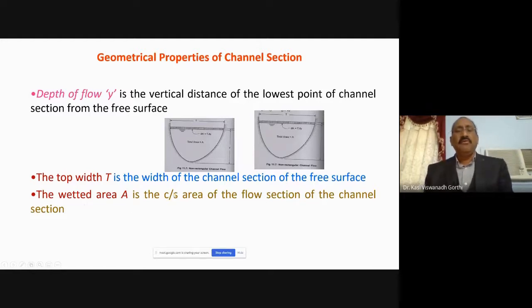So what is this wetted area? If you take the entire cross-sectional area of the flow section, it is called the wetted area. Entire thing in the figure would be the cross-sectional area of the flow. So this cross-sectional area of the flow section is called the wetted area A. Depth of flow Y, top width T, wetted area A.